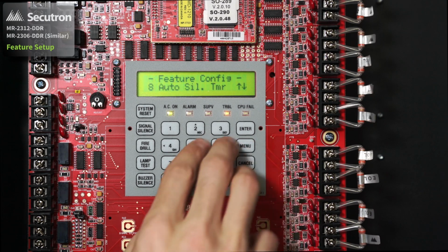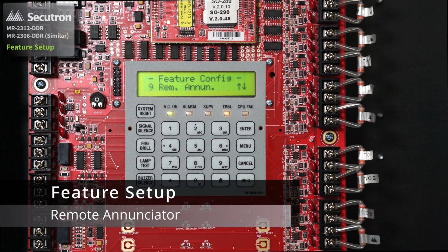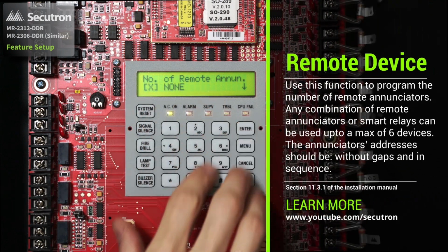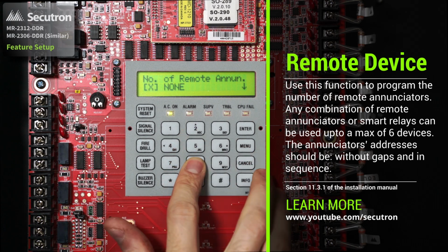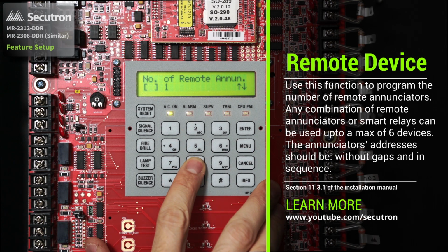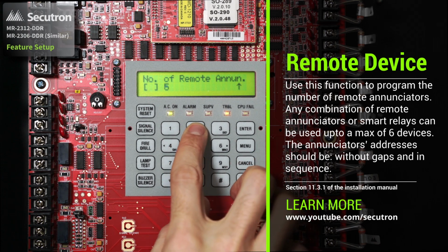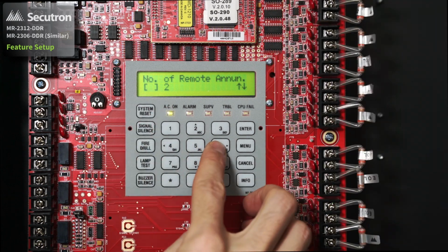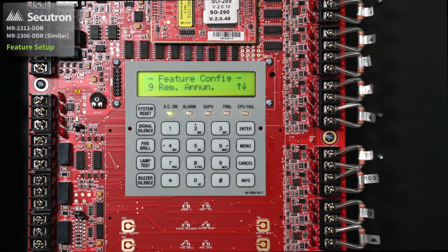We can go back and go to the next feature. Next feature is the remote annunciator or smart relays. By selecting this, we can have the number of remote annunciators or relays. Right now, by default, is selected to none. We can then scroll through these to say that we either have 1, 2, 3, 4, 5, or 6 remote annunciators. Once we've found the desired number of annunciators that we'll be adding in, we can hit the left or right cursor to apply the X. Once the X is applied, we can step out of that feature.